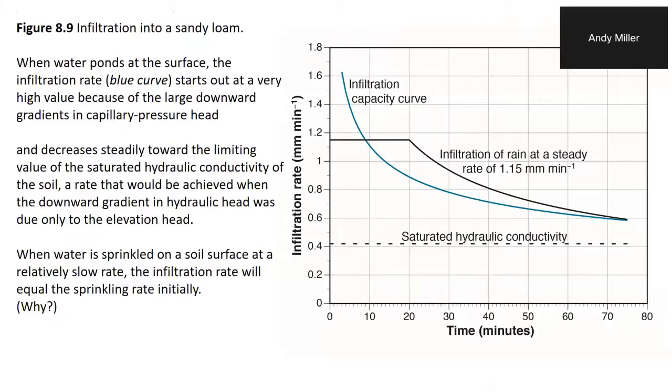Are we doing okay? Does it make sense? Yes? Yes. So you just said that the rain rate usually exceeds the infiltration. Well, it doesn't actually. Let's put it this way: it depends on where you live, right? If you live in a nice forested landscape with deep soils, lots of organic matter, and it's not packed clay or something, then it takes a very big storm to generate enough water that it actually accumulates at the surface. If you live in my backyard, which was part of a suburban subdivision where they removed most of the topsoil and it was hard packed, almost every time it rains, water runs off the surface because it's got very little infiltration capacity left.